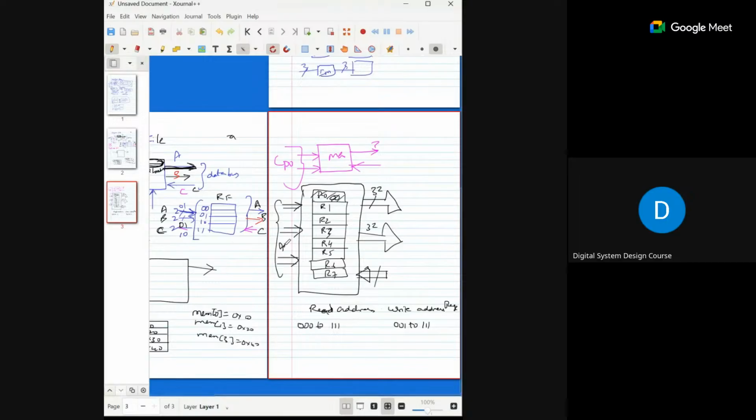These are my address lines. So it is a writing process. For the writing, I have to pass the data in this bus only. So what is the length of data I am supposed to write here? 32 only, because every register inside the architecture is 32 bit. I can give any different number. This area I can read from read data.